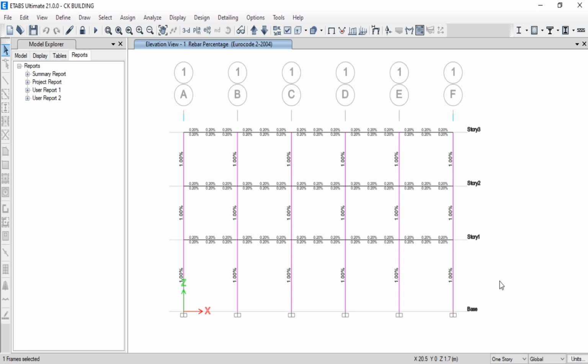For a rebar percent to be safe, it should be less than 3, or not more than 2.5%, to avoid failures in columns. And when the design rebar is less, it is easy to concrete and vibrate these columns shown here.